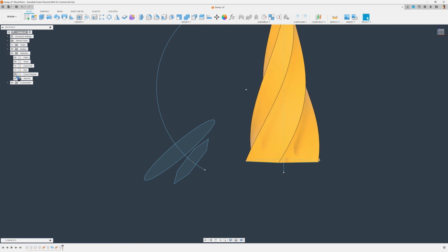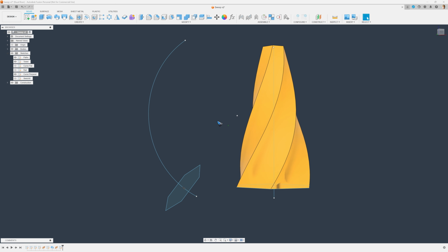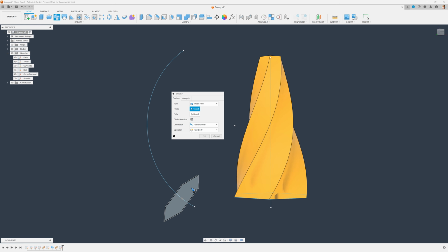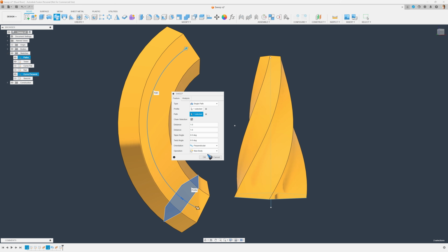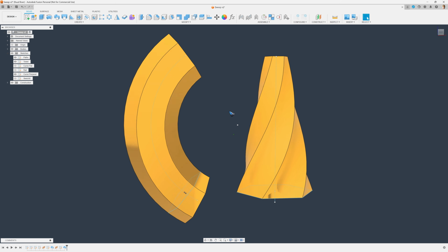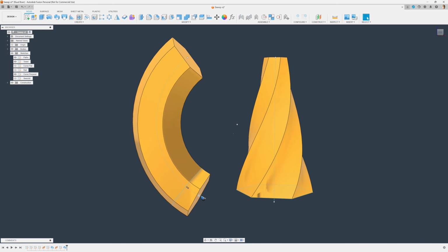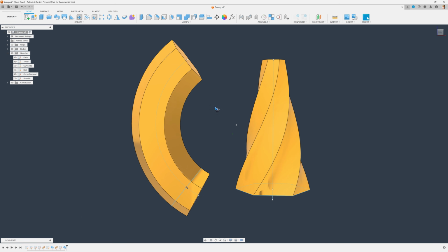that path. Okay, let me close that down. Let me now start the sweep tool. Sweep, select the hexagon, select the path, and now we get a perfect hexagonal sweep along our curve, and this is what you would expect that would happen.